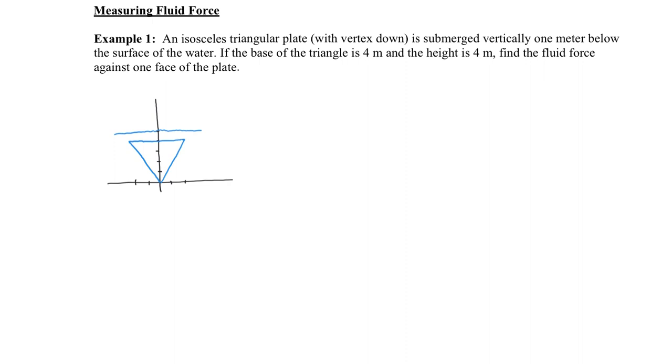All right, so what we're going to do is just consider a little sample strip here, like a little rectangular strip. And we're going to find the fluid force against this sample strip. Also, I probably should have mentioned the title of this section is hydrostatic pressure and force. So hydrostatic, hydro meaning liquid, static meaning at rest. So the liquid's at rest, so it's just sitting there. Okay, so we're going to find the fluid force against this little strip, and then we'll integrate to find the force against all these strips on this plate.